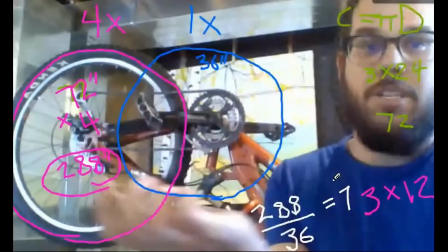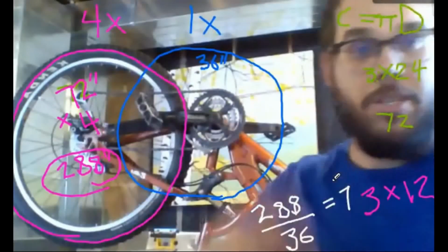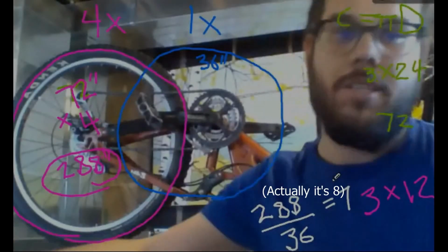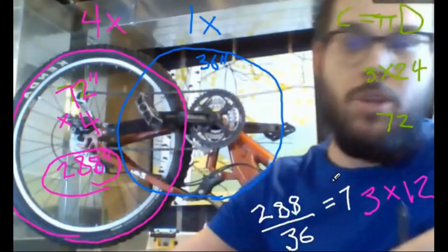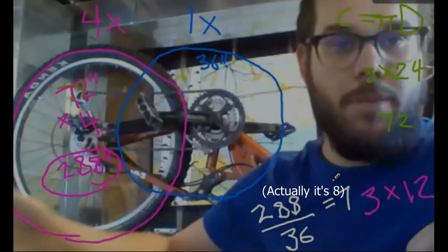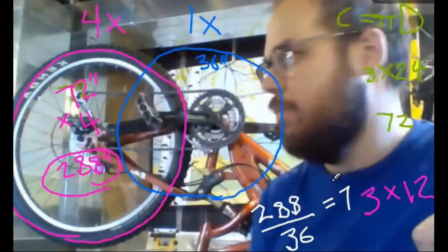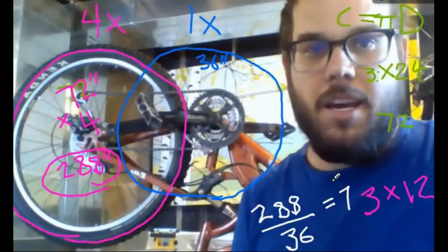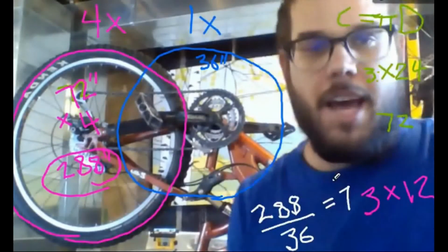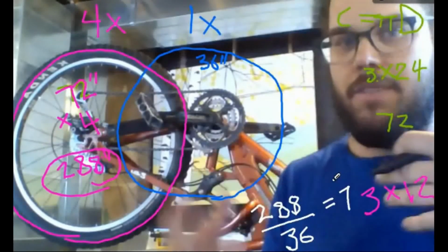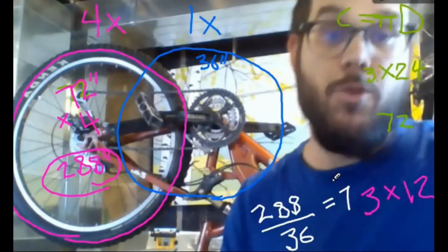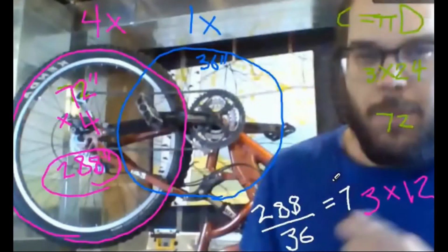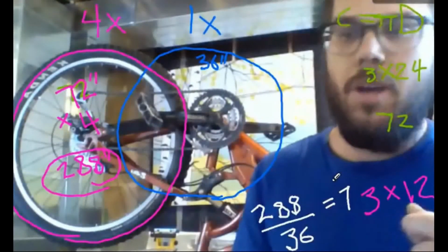The disadvantage then is that it's going to be making you weaker. So it makes you go 7 times faster, but it's going to take 7 times more force to do that, which is why it's bad to bike uphill in that high gear, for example. So that's kind of the idea of the most advanced level of analyzing these systems, right? Is starting to look at the different parts and the ratios that they move with, and starting to talk about calculating mechanical advantage, speed ratio, or efficiency.